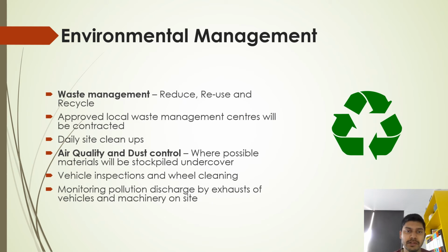So looking at the environmental management, we broke it down to two key areas: waste management and air quality and dust control. Waste management will revolve around the principle of reduce, reuse, and recycle. So waste such as concrete, scrap metal, and timber will be stored on site, and they will be reused whenever possible. Waste that we can't reuse or recycle will be transferred to waste processing centers nearby. Our team will conduct regular cleanups on site to ensure that there will be no loose rubbish present on site, and bins on site will be emptied daily.